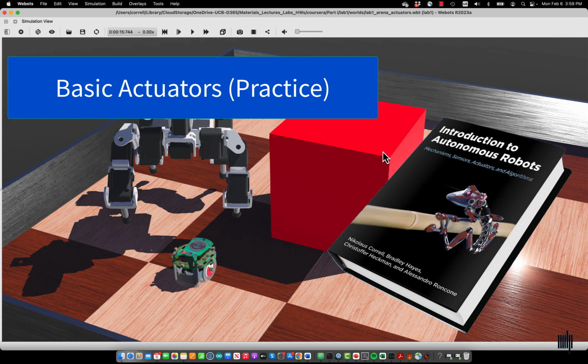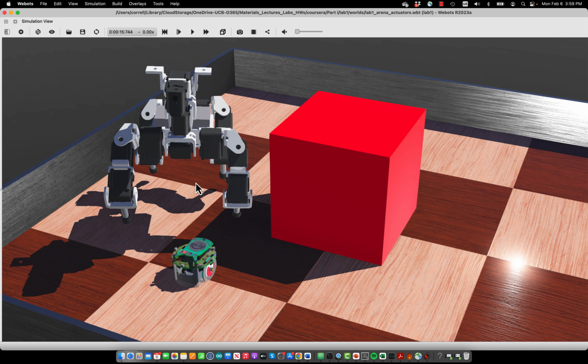So now that we have introduced the nomenclature, I can probably tell you how the motors in these two robots work. The e-puck is very small, and you are interested in knowing exactly where the wheels are at every time. And you cannot afford an expensive mechanism that involves an encoder. So people usually choose stepper motors for small robots like this.